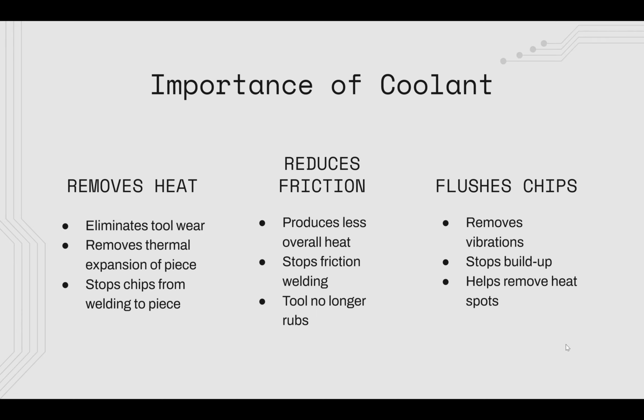To elaborate, the importance of coolant is that it removes heat by both reducing friction and eliminating part heat. Thus, there is no thermal expansion of the piece, allowing tight tolerances to be reached. Without friction, the passes can be much cleaner and provide a good surface finish. Chips can also be flushed out. This removes vibrations and hot spots, which may damage the integrity of the piece through continued machining. Under the circumstances, tool life is also greatly increased.